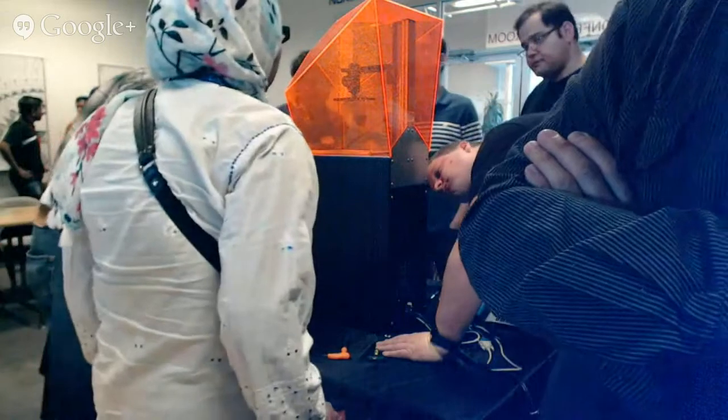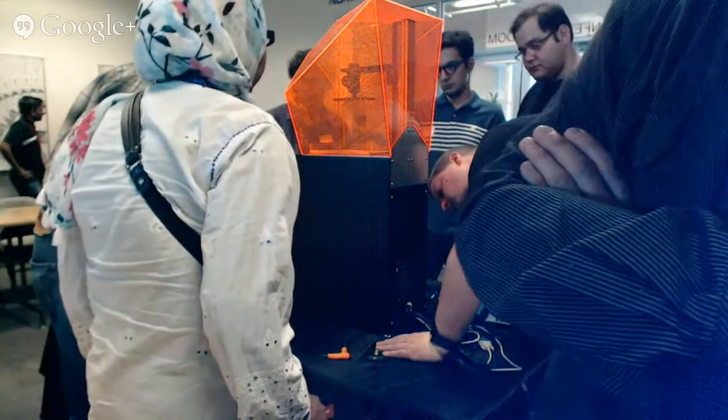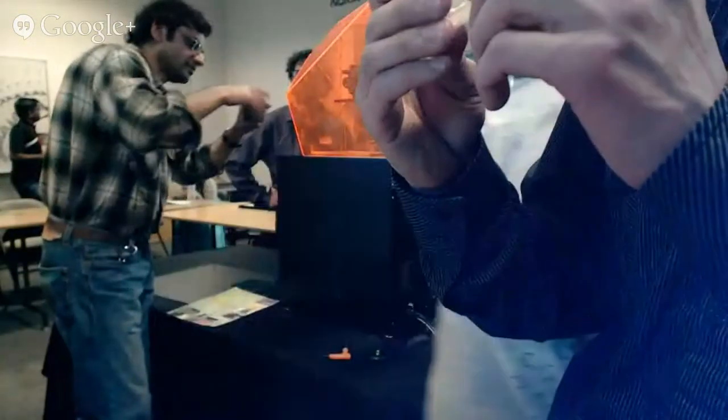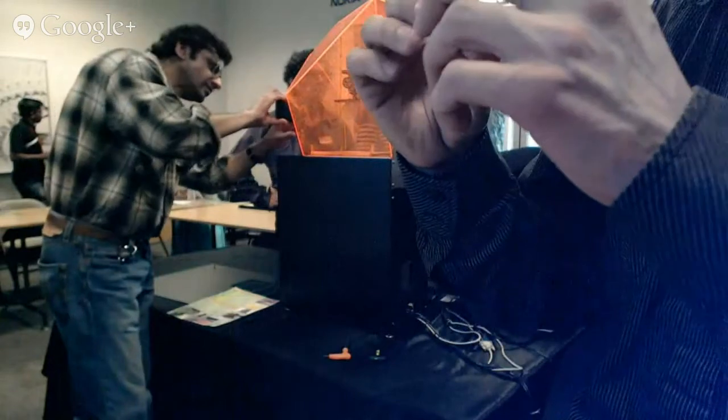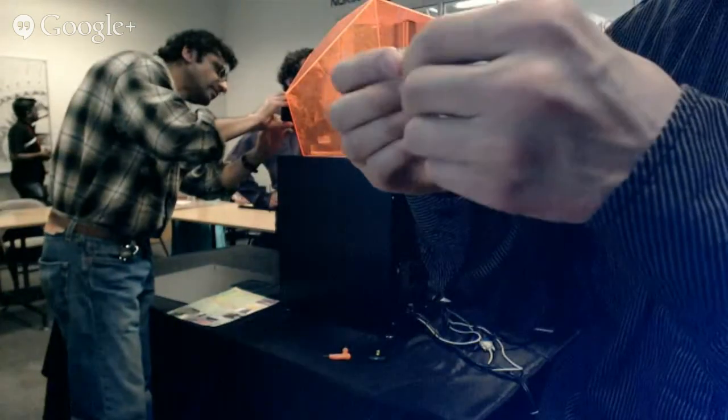The vat is made out of a couple of different things. If you look at it, you'll see that it's got soft film sides, right? And that's a unique feature of the vat, the film sides, because the vat needs to flex, right? Because when we release, we don't want to just pull the part off the top, because then we'll have to counteract all the vacuum force all at once. We want to peel it off, right? So we're holding it onto this side, and it's lifting, and that's going to cause the vat to flex, right? So this film is really important because the film allows us to flex in this direction.